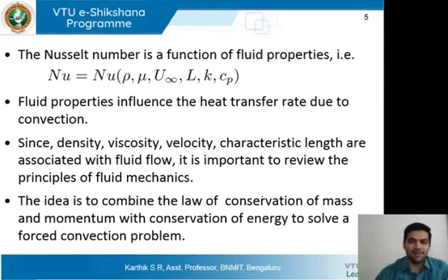So here what we will do is we will take up the conservation of mass and momentum, which are related to fluid flow, and we will couple it with conservation of energy, which will give us the solution to our forced convective heat transfer problem. Conservation of mass and momentum will actually give you the velocity profile and also the drag force, skin friction coefficient for a flow problem.